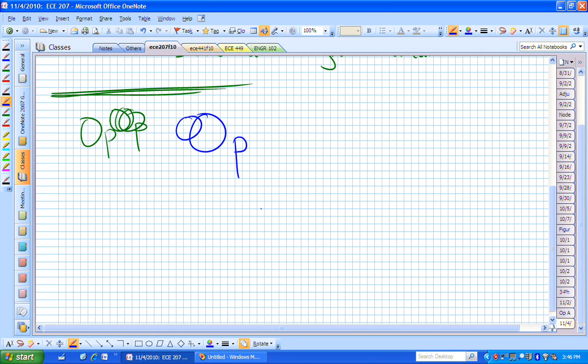Now that we have this in an interconnected network, it's not going to be strictly that large. This R sub f will actually knock that down, but what we're doing here is seeing in which direction V naught is moving relative to V sub x. We know V naught is A sub OL V sub d, but what do we know about V sub d and V sub x? They're just the negative of each other, aren't they?